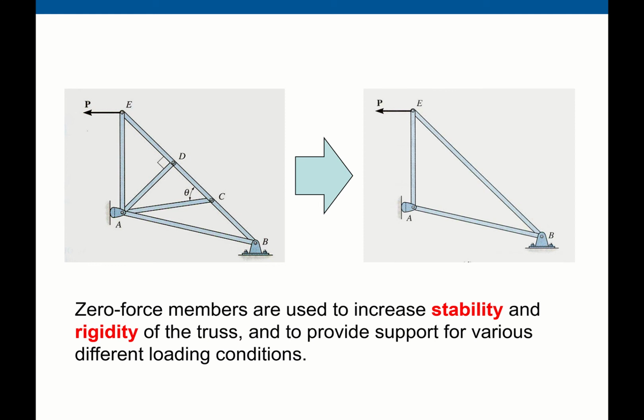Then you can ask, oh professor, why is a zero force member necessary? Because it's complicated and it makes the problem more complicated. Why do we need a zero force member? Yeah, that's a good question. Even though the zero force member does not carry any force, it is great for the stability and the rigidity of the truss.